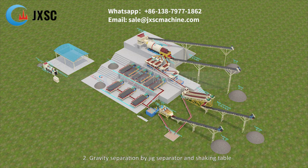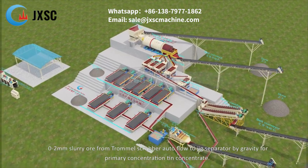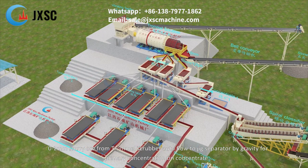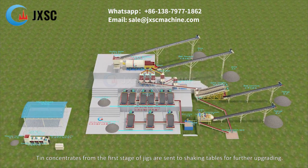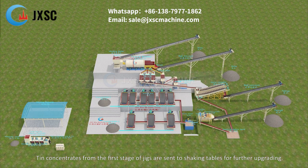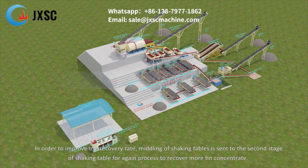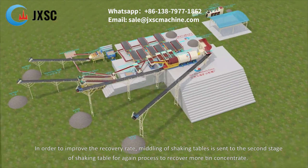2. Gravity separation by jig separator and shaking table. 0 to 2 mm slurry ore from trommel scrubber autoflow to jig separator by gravity for primary concentration of tin concentrate. Tin concentrates from the first stage of jigs are sent to shaking tables for further upgrading. In order to improve the recovery rate, middling of shaking tables is sent to the second stage of shaking table to be processed again to recover more tin concentrate.